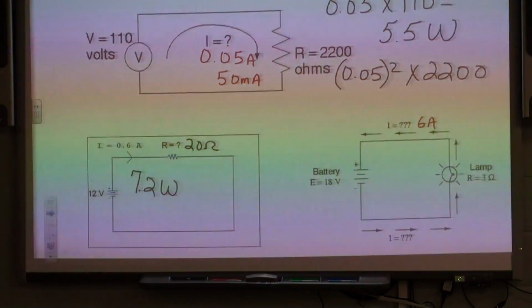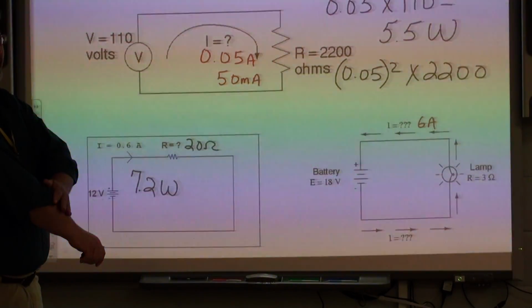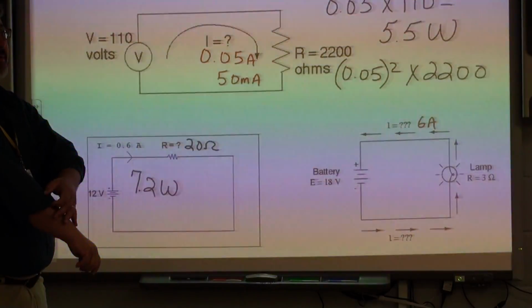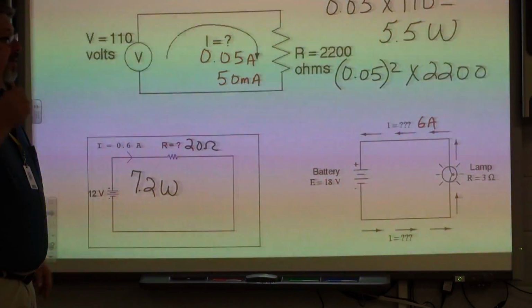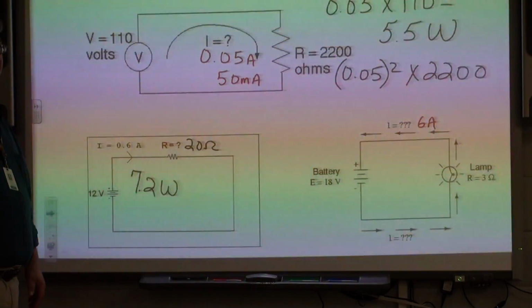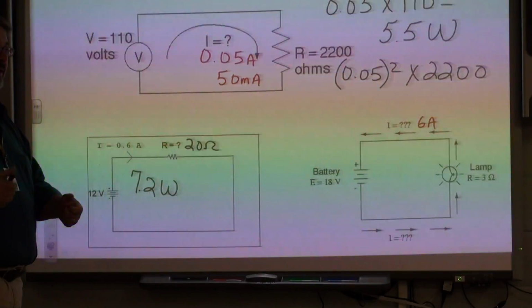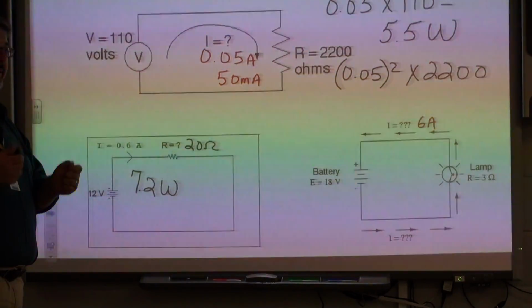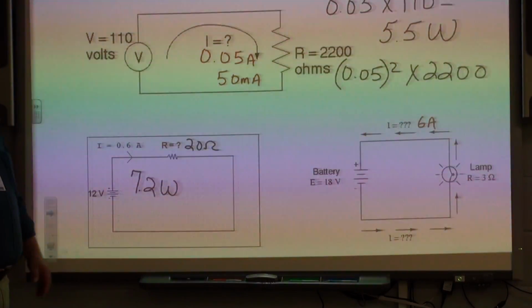Heat increases resistance, doesn't it? I think it actually lowers it on the bulb. We can try that and see. We'll do a hot bulb, cold bulb. It's been a while since I played with it. I think we did it with that little 12-volt lamp down there, and I think we found that if you heated it up, turned it off quick and measured, it actually lowered a little bit. But you gotta remember that's in a vacuum, so some properties may change.